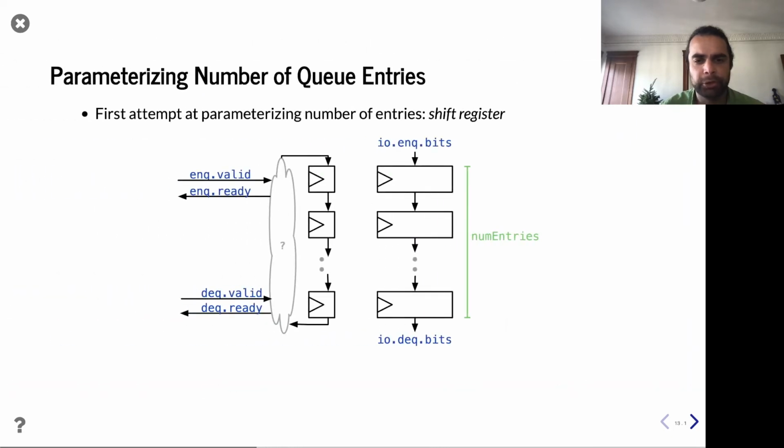Let's talk about one of the big shortcomings of this: the issue of bubbles. If I NQ and then I DQ, everything shifts down. But if I do that a few times and there are bubbles being pulled in by those DQs, and then I NQ again, we're going to have maybe a full entry, a bunch of empty entries, and maybe a full entry. So it's quite possible you have a mix of full and empty bits here, and these bubbles are going to be problematic.